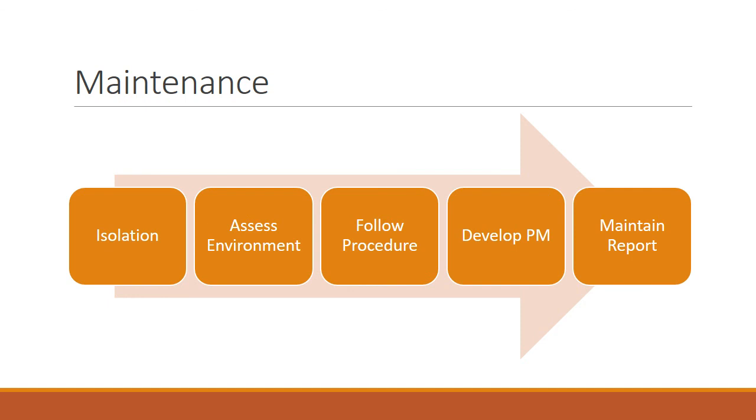And you should also be diligent and have a team to thoroughly check the results of these tests to make sure that your switchgear has the best preventive maintenance that it needs to prolong its life, as well as to make sure that any inherent condition that it has should be detected early on in its development stage.